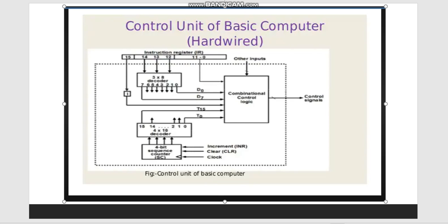The timing for all registers in the basic computer is controlled by a master clock generator. The clock pulses are applied to all flip-flops and registers in the system, including the flip-flops and registers in the control unit. The clock pulses do not change the state of a register unless the register is enabled by a control signal. The control signals are generated in the control unit and provide control inputs for the multiplexers in the common bus.